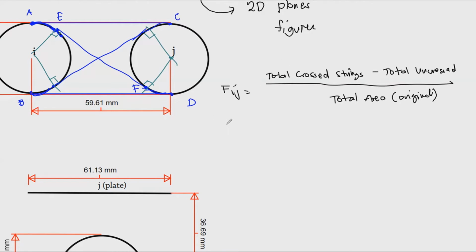But if we need to simplify this further, and usually in symmetric objects, we can say that Fij is simply the diagonal, because if the diagonals are the same, then we have two diagonals here and two sides, because we usually refer to the uncrossed strings as sides, and then we have the two area. And area here doesn't actually mean the dimension is meter squared, but the circumferential area if it's a circle, and the arc length if they are just the hemisphere.